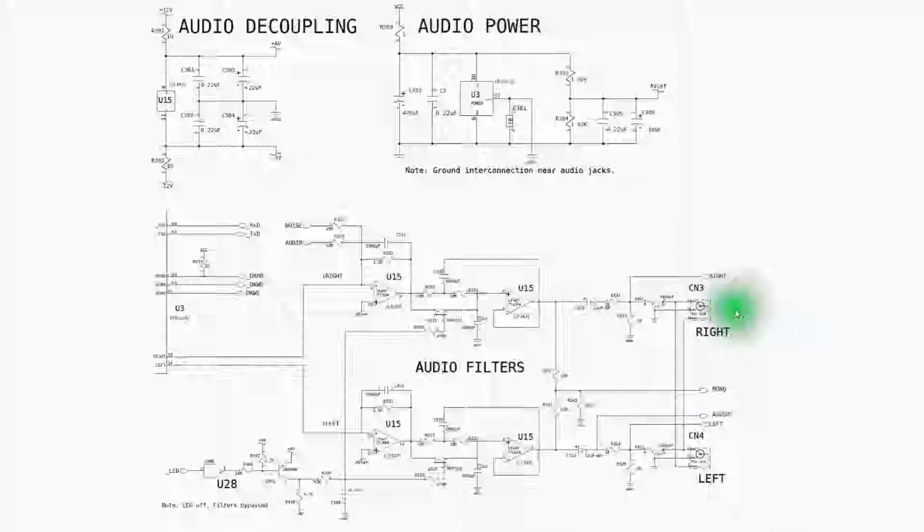So you get a mono audio out with only one RCA plug in here or with one RCA plug in here. If you plug both right and left into your amplifier, that bridging contact is opened up and you get stereo audio out. So this confused me for a long time because I'd plug in one speaker and it would work. I'd plug in the other speaker and it would appear to work. I'd plug both in, and I believe the right channel is the one that cuts out. I don't know for sure. And finally I found the schematics and this little bridging circuit and came to understand why.